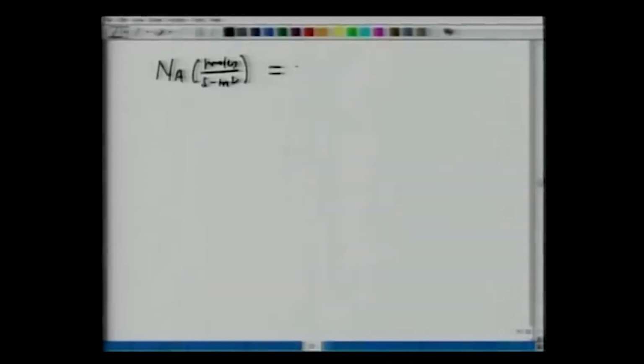So we would like to sum up the lecture with the governing equation which will form the basis to address a variety of diffusion problems. If you recall, we said the total flux as observed by a stationary observer, N_A, will have two components. One is the bulk transport, which we can write as V_A C_A, where V_A is the molar velocity of component A. This will also equal x_A N. The first component is bulk transport, and the second component is your molecular diffusion.